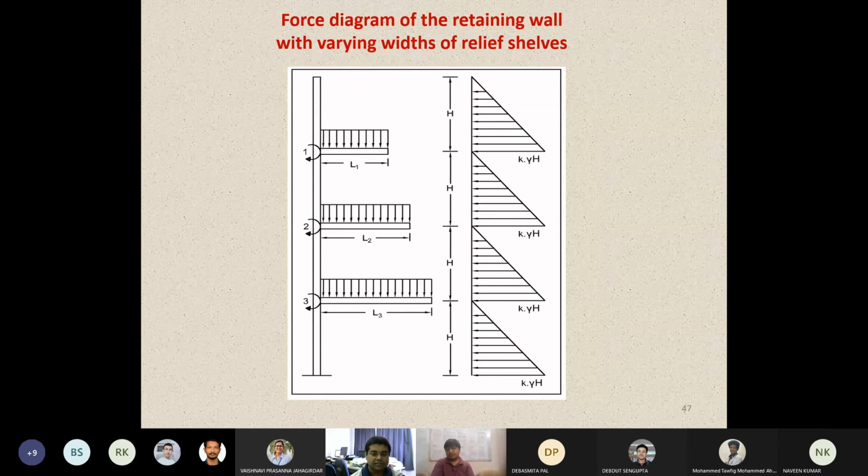And when your percentage of steel increases, the spalling of concrete starts taking place very easily. And when this spalling takes place, that basically generates a crack. In the case study which you are showing, the crack was all along that shelf. So that's where I was getting some doubt whether the development or the anchorage length also was properly done or not. By design, it may be done, but whether in workmanship they have done or not.